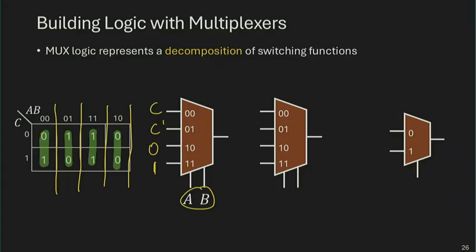All right. And let's also try something different. Let's say if I use A and C to cut my K-map, which is perfectly doable. You don't have to restrict yourself to any 2 particular variables. You can use any variables as the selection signal and the other variable as some of these input signals. So if you cut it by A and C,